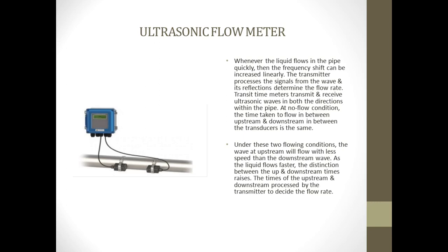Piezoelectric crystals are used as both transmitter and receiver. In a transmitter, electric energy in the form of a short burst of high frequency voltage is applied to a crystal, causing it to vibrate. If the crystal is in contact with the fluid, the vibration will be communicated to the fluid and propagated through it.